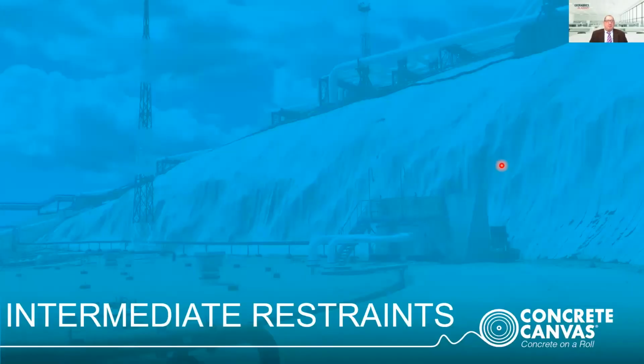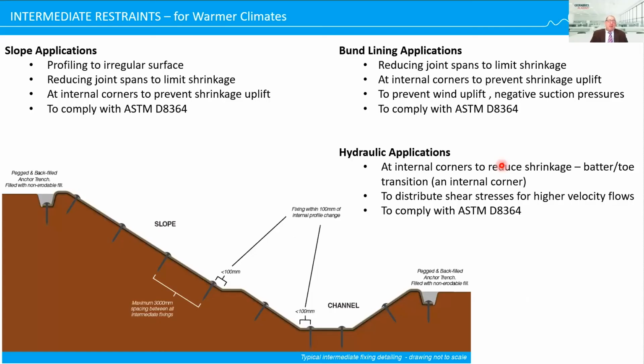Intermediate restraints. Now, what happens is, in these typical applications, we use intermediate restraints along the slopes and the different sections for different applications. In slope applications, we use it to profile irregular surfaces. We use intermediate fixings to reduce joint spans to limit shrinkage. We use it at internal corners to prevent shrinkage uplift. And as you remember those notes earlier, I explained to comply with ASTM D8364 requirements of slopes.